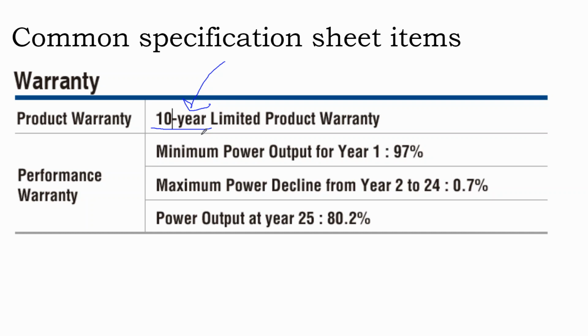In a very high-cost electricity market with very expensive real estate, it generally is worthwhile to go top shelf. If you are in an area where the real estate's cheap and you can just do a really large solar array, then go in with lower efficiency modules, cheaper modules. If the rooftop's very accessible and you can get on the roof and get off the roof, if it's a ground mount array where you can get on and off the array site with ease, going lower end is perfectly fine too.